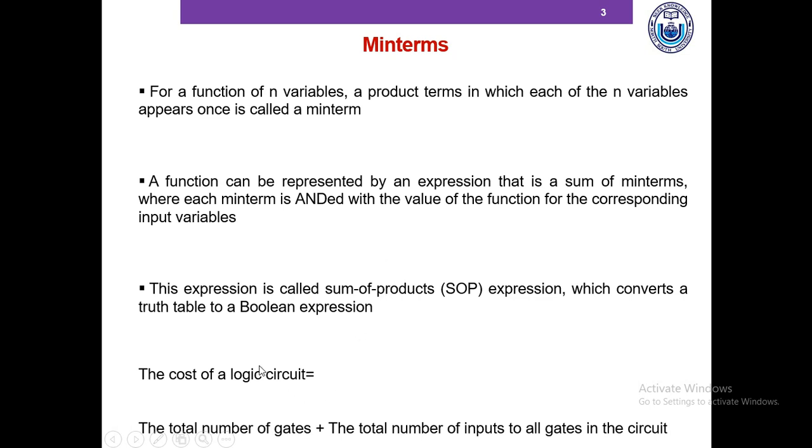And this is the formula to compute the cost of a logic circuit. The cost of a logic circuit is equal to the total number of gates used in the design plus the total number of inputs to all gates in the circuit.